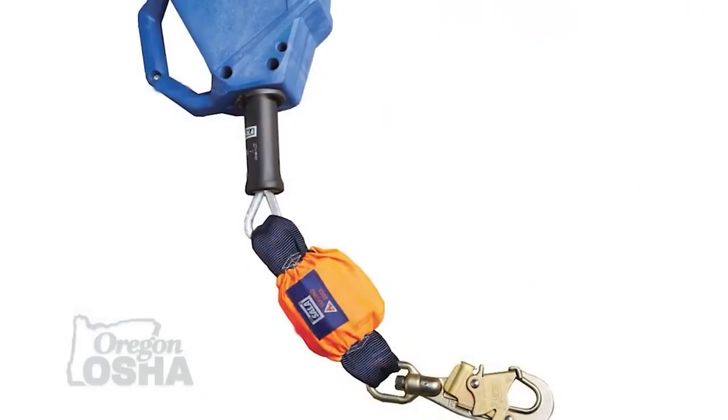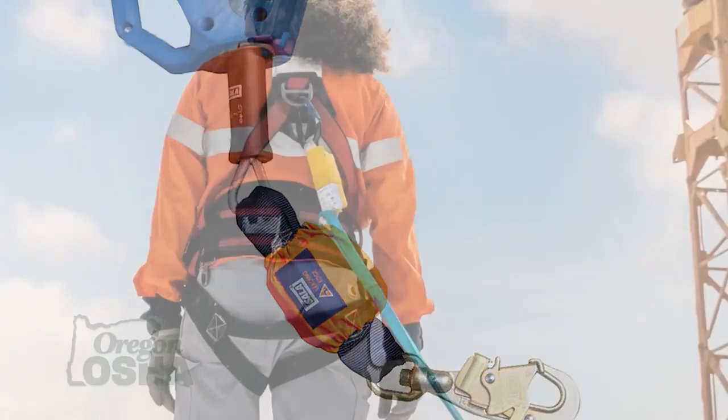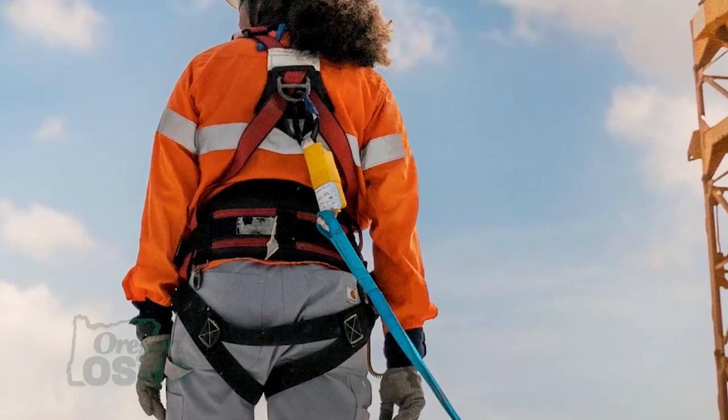When we're working in a situation where we have a leading edge, we have to make sure that our arresting device stays with the worker themselves. When we're working with a fall arrest lanyard, that means making sure that the shock pack, the shock absorbing device on that lanyard, is always attached to the worker's back D-ring.